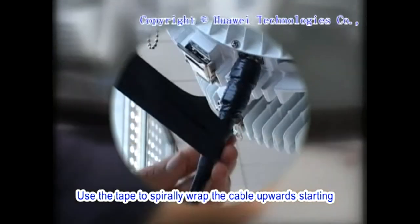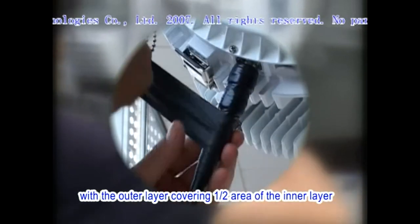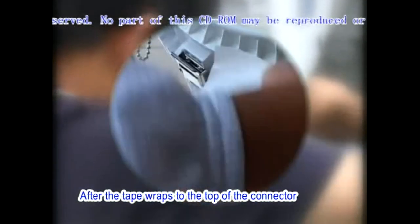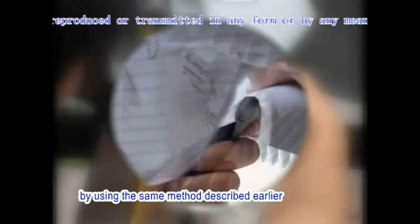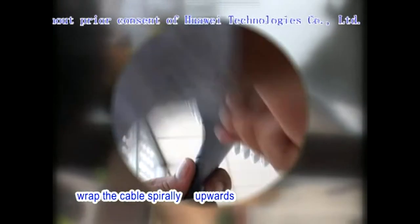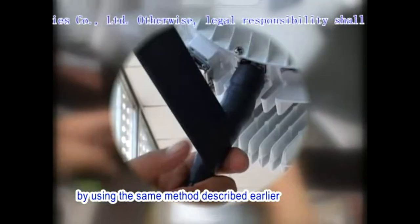Use the tape to spirally wrap the cable upwards starting from 5 cm below the connector, with the outer layer covering half area of the inner layer. After the tape wraps to the top of the connector, wrap the cable spirally downwards by using the same method described earlier. After the tape wraps to 2 to 5 cm below the connector, wrap the cable spirally upwards by using the same method described earlier.